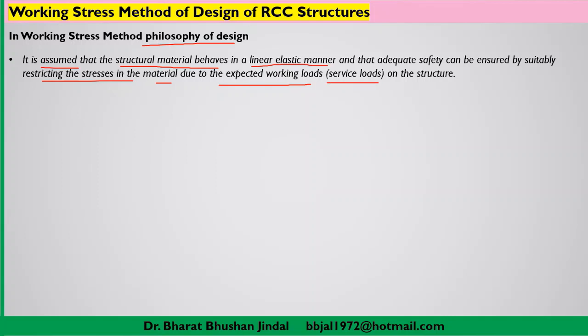it is assumed that the structural material behaves in a linearly elastic manner. This is our assumption in the working stress method, and we are restricting the stresses so that whatever loads come on the structure will not fail the structure.